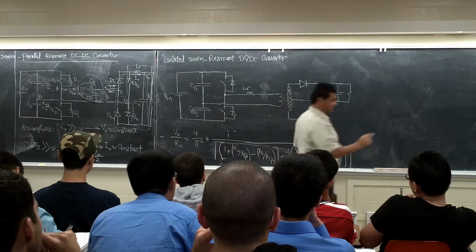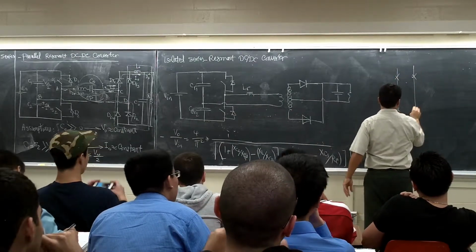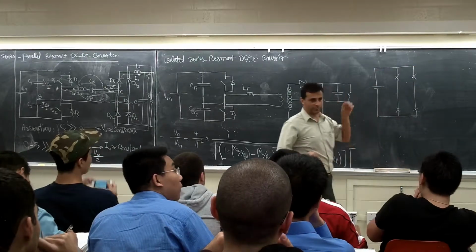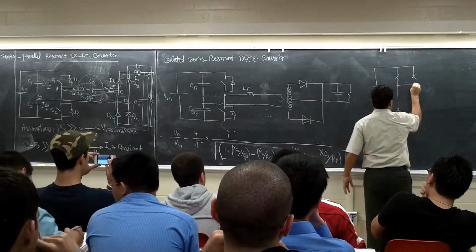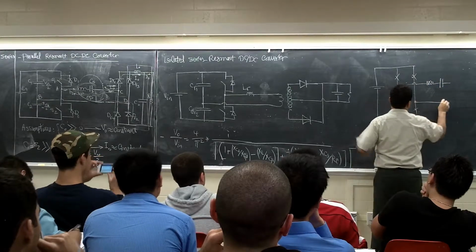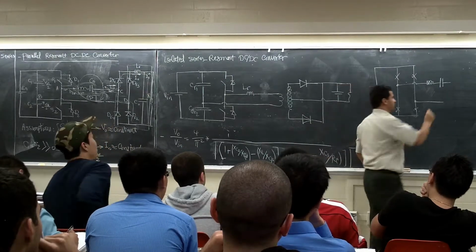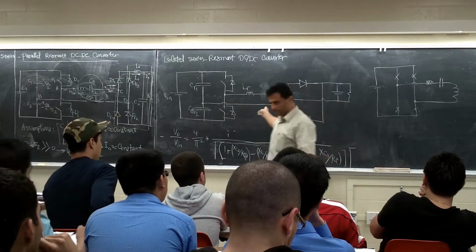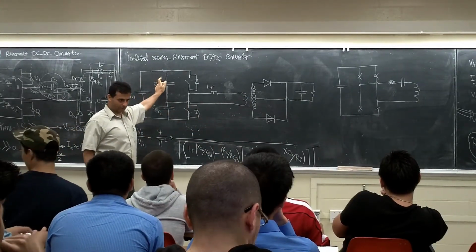If it was a full bridge, see, this is a full bridge, right? All we discussed was a half bridge. You put a half bridge, but it could be a full bridge, right? If it's a full bridge, you have to have both, because there is no capacitor here to use for resonance. You have to have the capacitor here. But if it's a half bridge, to create the half wave voltage here, you have to use this capacitor.